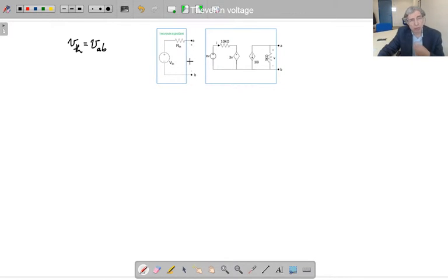So that's the rule. How am I going to apply that rule? We've got to go back to the given circuit. This is open circuit, nothing connected to it, no current passing through here. And when it is open circuit, I am going to calculate that VAB. In this example, this open circuit voltage is an element voltage at the same time. In some other examples, this voltage may not be an element voltage. It could be more than one element voltage in some cases. But in this one, it is simple and it is an element voltage.